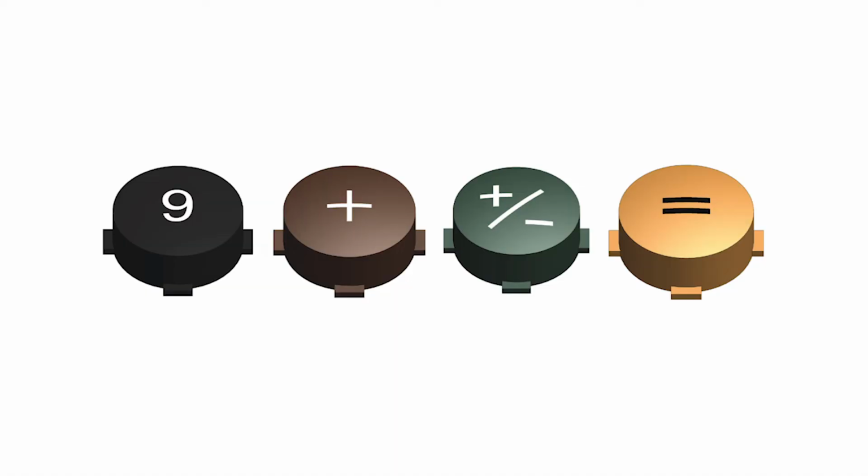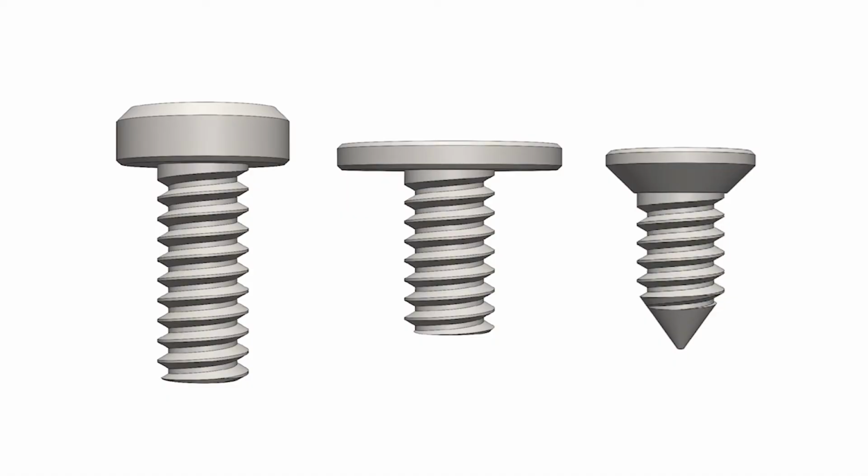The next item is critically important, and that is the information about design tables. What is a design table? So first of all, whenever we make a CAD model, and the CAD models you've made so far, there is one sort of default configuration for that model that you created. But in the background of the CAD system, you can create alternative configurations. You might have, for example, like an ET66 button that's yellow or brown or green. Those are all different configurations. Or you might have a part like a screw, and one configuration is long and one configuration is short, and one configuration has a Phillips head and one configuration has a standard flat head. And you can create all those in design tables.